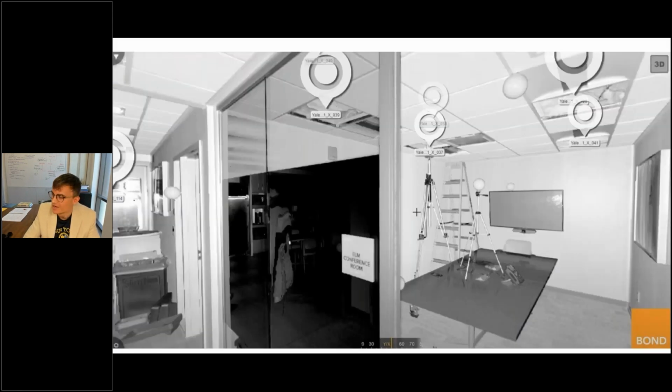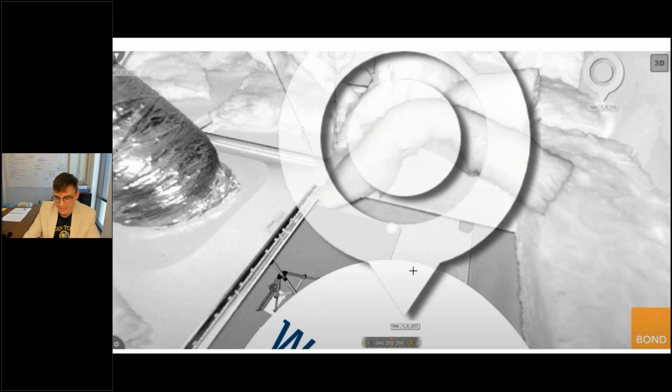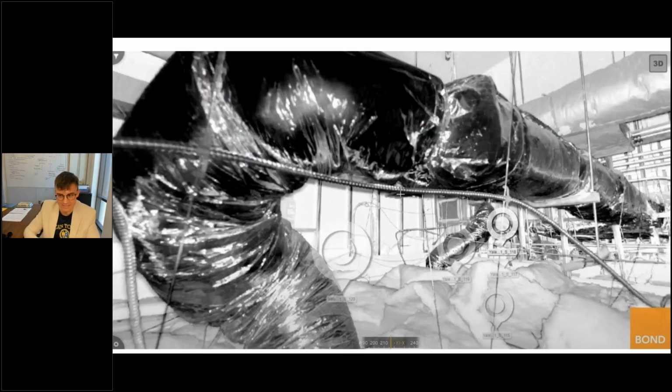Scanning above ceiling requires that you pop ceiling tiles, and it's very similar to the doorway concept. These tile openings are critical for tying what's below to what's above. Use a high-low pattern for this. So it's 3 scans stacked. One below the ceiling to capture the room, one at tile level, and then one above the ceiling to capture all the above ceiling stuff. These 3 scans together facilitate registration.